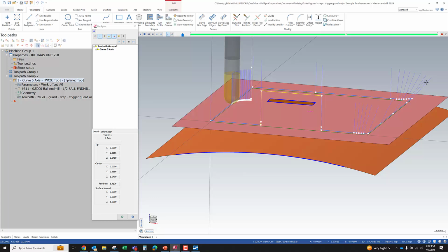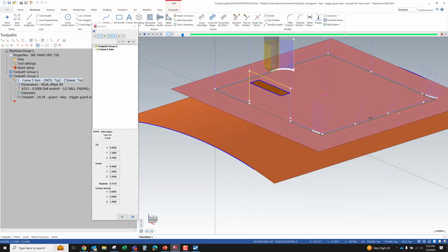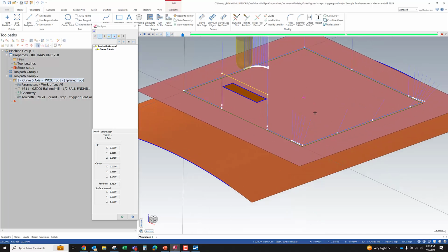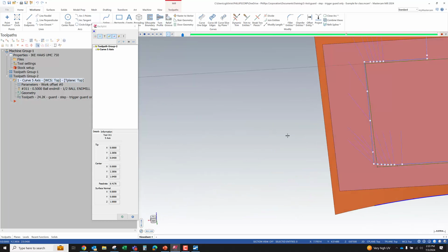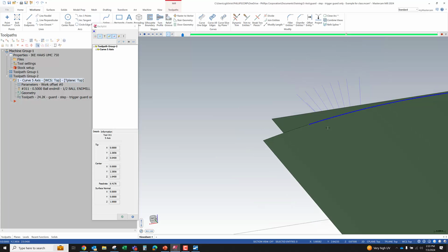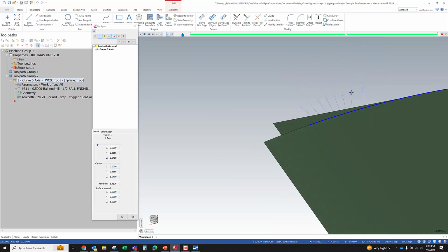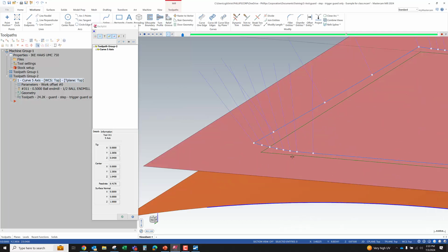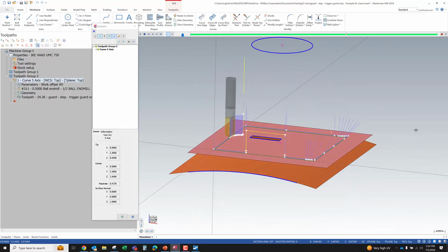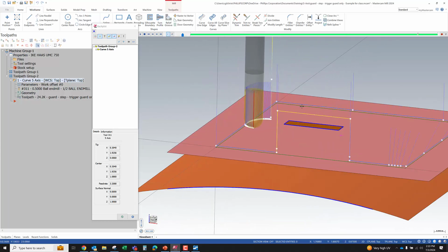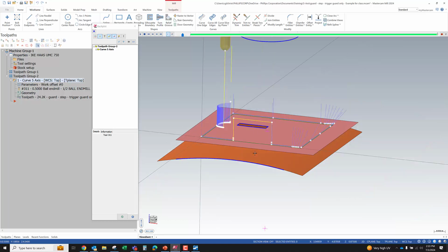And believe it or not, even with this kind of much fewer vector lines, this would actually probably rotate really well. And part of the reason I say that is because even with the settings we're using, there's a fairly consistent amount of step and angle change. A little bit more here, probably not enough to be concerning. And kind of the same thing over here, right? What I'm looking at is the smoothness and the step size between those vectors, the amount of change on the tip. That's all well within acceptable limits and results. So this would actually, if we had to do a path like this, cut really nice.